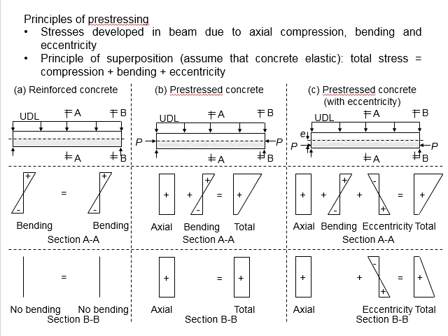In fact, these principles can be applied for various cases of the prestressing conditions. For example, for an external load other than UDL, such as point load, you will need to first determine the bending moment diagram and find the locations with the maximum and minimum bending moment.